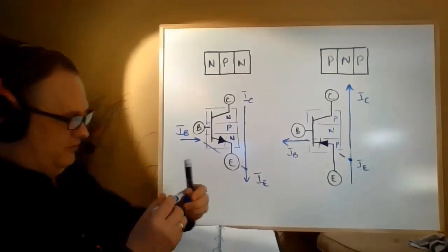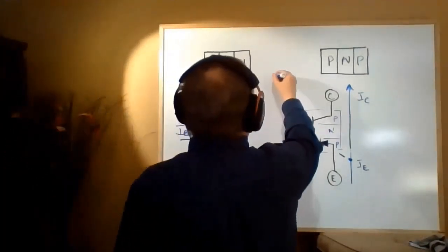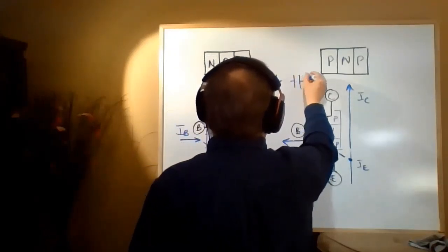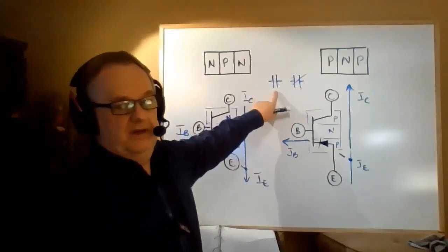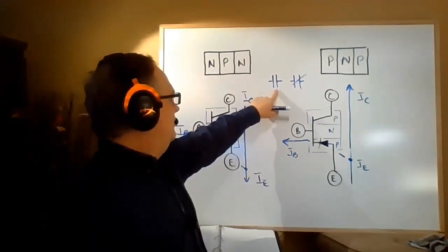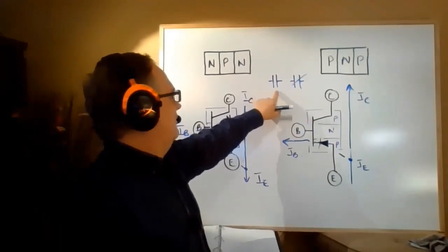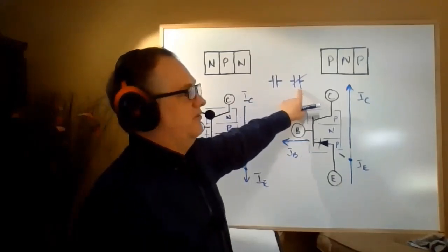So it's very similar to looking at something like a contact. We're used to looking at these. This contact we would say is normally open when de-energized, so it's open when de-energized, and then it closes when you energize. Whereas this one is closed when it's de-energized, and then opens when you energize.